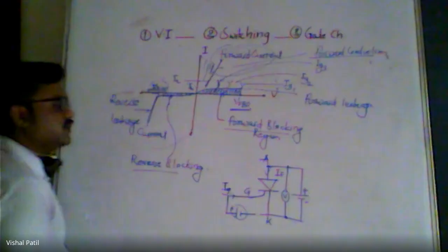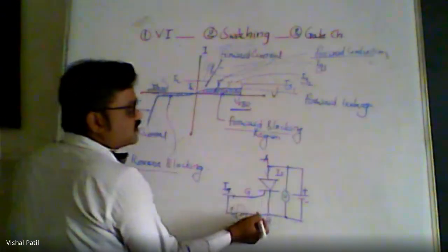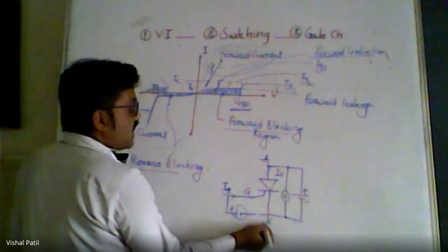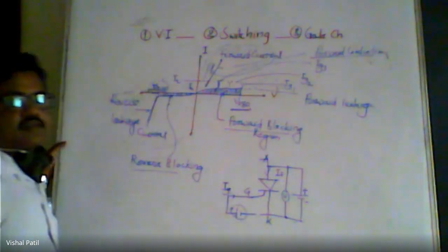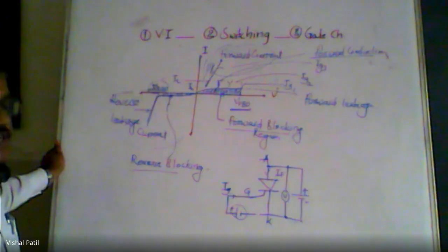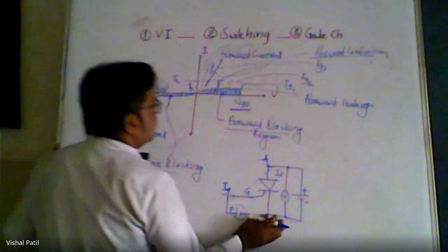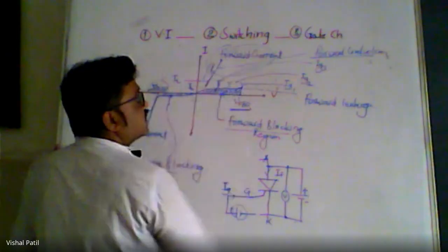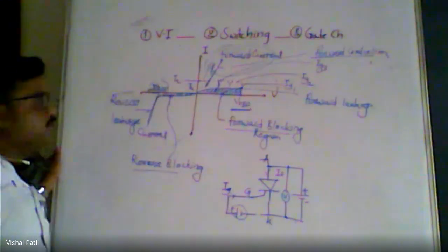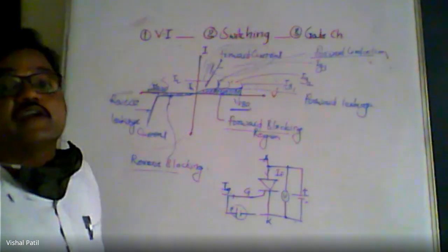If we go on increasing the voltage and changing the current, what happens? Suppose the thyristor is in forward bias, anode to cathode, and we are applying different gate current values to the gate terminal. As we go on increasing the forward voltage, at a particular voltage junction J2 breaks down and the forward current will start to conduct. That is, it is about to enter the conduction mode.